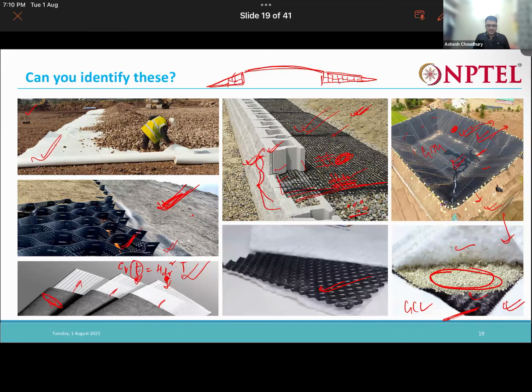You will see that on the sides in the approaches, these blocks are just fascias, right? Behind these fascias, between these fascias, there is nothing but reinforced soil. So the soil is reinforced either with the use of steel strips, or with the help of geogrid or geosynthetic, or any kind of reinforcing material. So these are actually used.